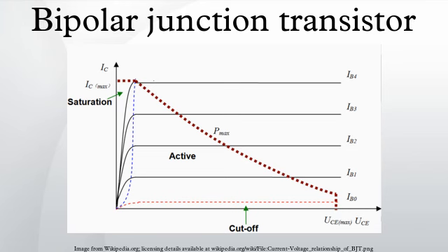The grading of composition in the base, for example, by progressively increasing the amount of germanium in a SiGe transistor, causes a gradient in bandgap in the neutral base, denoted in the figure by ΔΦg, providing a built-in field that assists electron transport across the base. That drift component of transport aids the normal diffusive transport, increasing the frequency response of the transistor by shortening the transit time across the base.